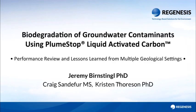The typical range of concentrations that we would look at the use of PlumeStop for would be below 10 milligrams per litre, and as you get down to 1 milligram per litre and below, it becomes even more efficient. So yes, we've treated sites at 20 ppm and so on, but around about 10 and below is typically the range that we'd look at. With hydrocarbon sites, beware of overlooked mass. They can become a problem as well, excess sorbed mass. So 10 ppm and below would be the target zones, and 1 ppm and below it'll become increasingly efficient. 100 micrograms per litre and below it's scorchingly efficient.